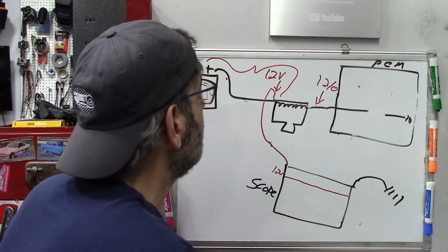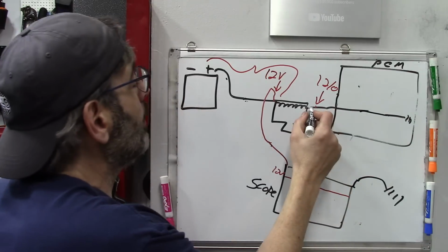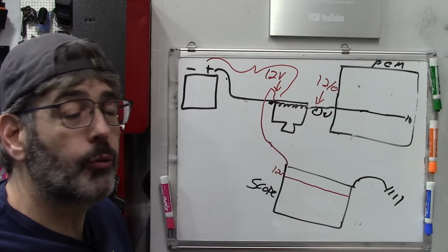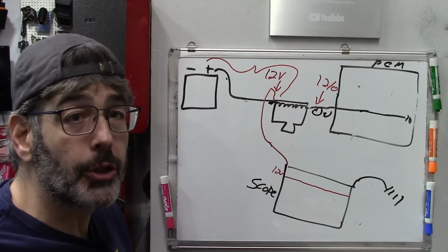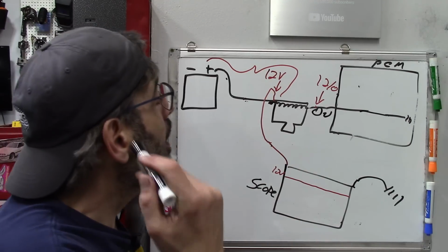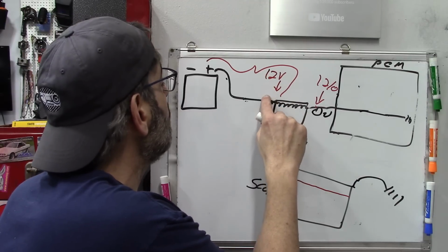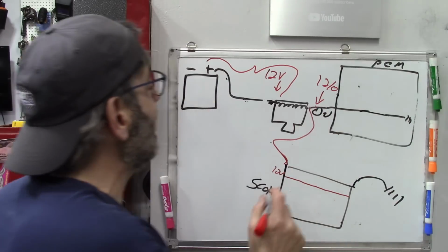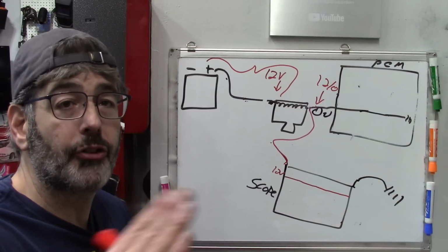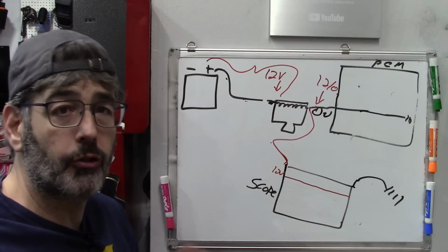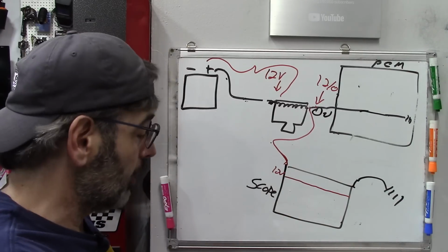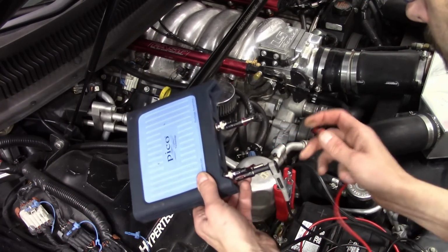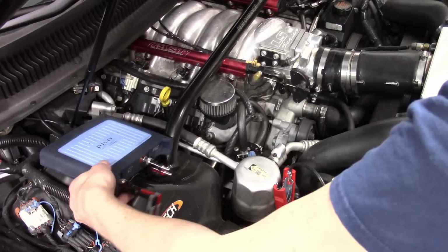If this switch closes, again, we will have 0 volts here. We still have 12 volts here, whether the switch is open or closed. That's where we're measuring. We're always going to have 12 volts. That's why it's important to understand why we want that lead to be on this side, because we know that's the side that's going to alternate 12 volts or 0, depending whether our switch is open or closed. Makes sense now? So let's go ahead and do that. We're going to go to channel A on my picoscope here, connecting to positive and negative.